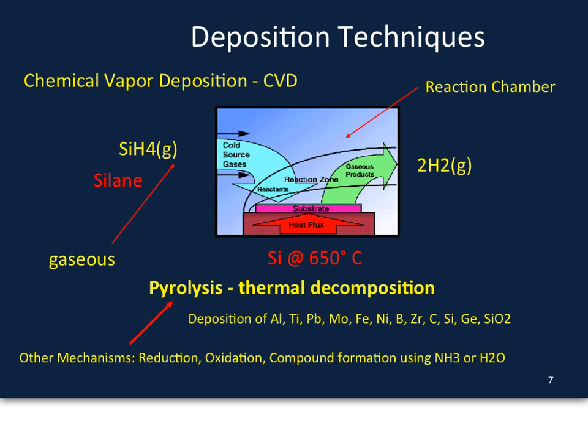In this case, the element to be deposited is silicon dioxide, and so you use this silane gas as your source gas. That precursor gas then reacts in this hot reaction zone and decomposes the material onto the substrate to produce the desired composite material on the substrate. And then the gaseous byproducts are ventilated away.